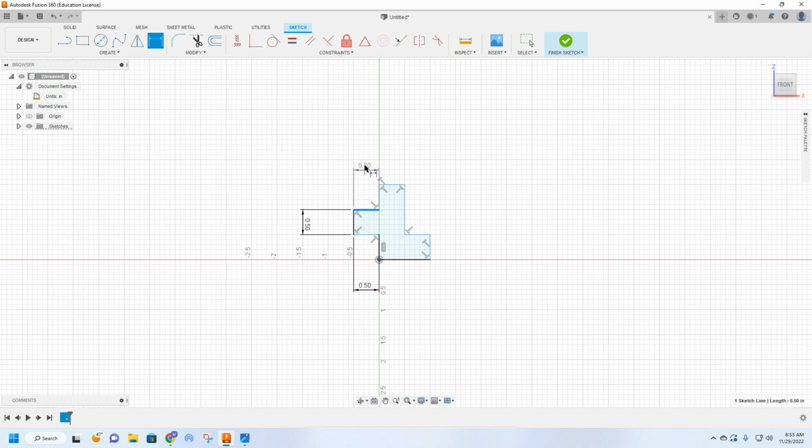And so now, if it's already the correct size, you can just hit enter. I'm going through and making sure that all of my lines have dimensions on them. Notice how the entire sketch has a black outline. That means it's what's called fully constrained, and nothing can happen. Now, to back out of a tool, I'm going to hit escape. And escape just kind of brings me back to this home menu.